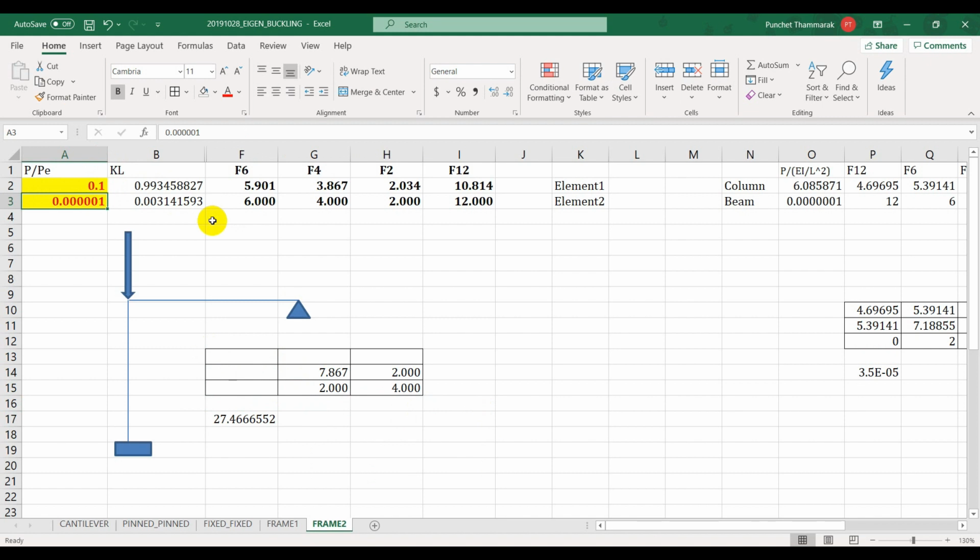Let's guesstimate first. This one is like the case where you have fixed and pin roller, okay, at the top. That case, the effective length is about 0.7, right? 0.7, when you square it up, you get about 0.49, which is 0.5. 0.5 is the denominator, so your buckling load of this case is going to be 2 pi square, approximately.